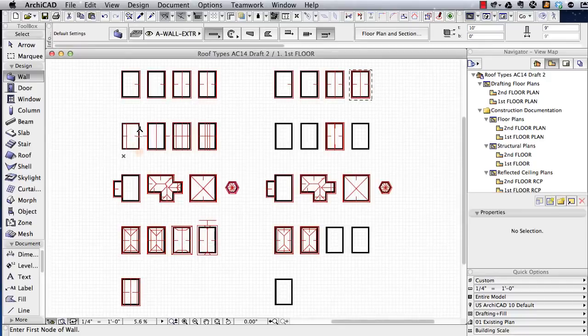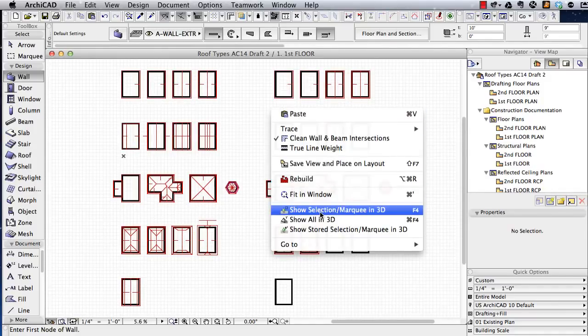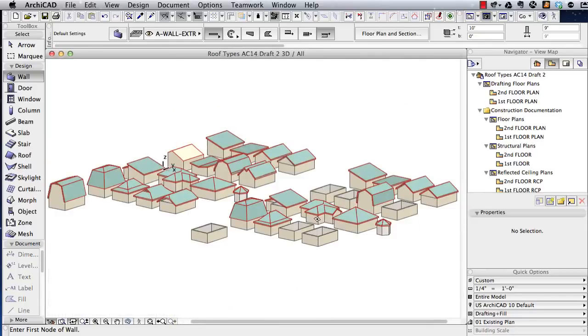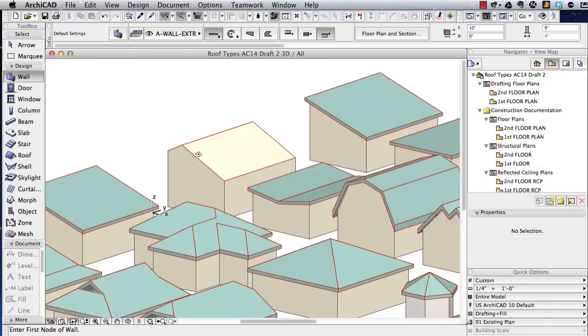Now we'll look at another set of roofs that one would think you'd be able to do easily with the Polyroof, the MultiPlane Roof tool, but actually are a little bit tricky. You have to break them up into pieces. So I'm going to take a look in 3D. For example, we have this salt box roof and we have the butterfly roof, and there are issues in terms of doing them with the new MultiPlane Roof tool.